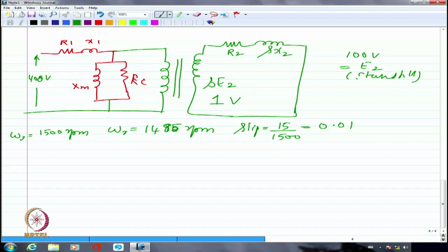Whatever is the minimum current that is needed, first of all, to develop that minimum torque, frictional torque, and also to establish the flux. Xm will require some current to establish the flux. So you will see that as the induction motor starts, the current falls very rapidly because of this particular reason. Now, this is I2. I am calling this as the rotor current.